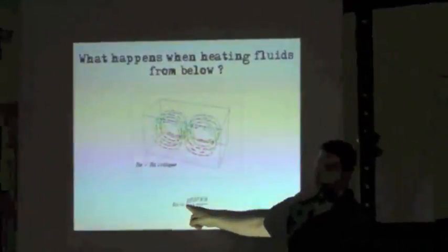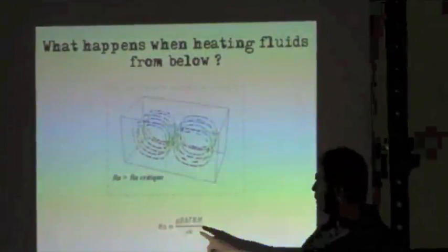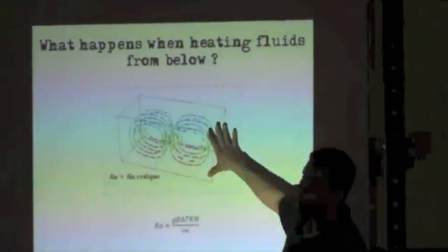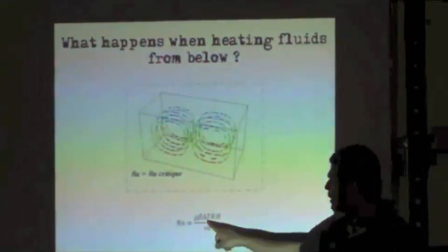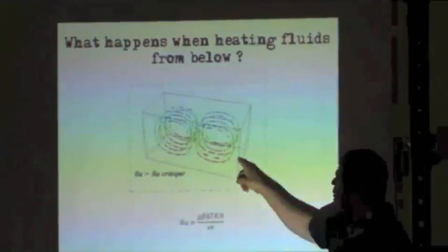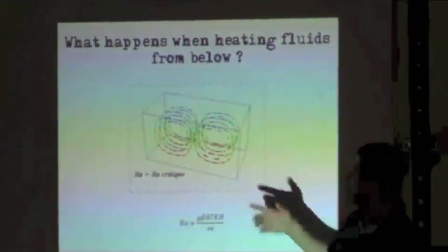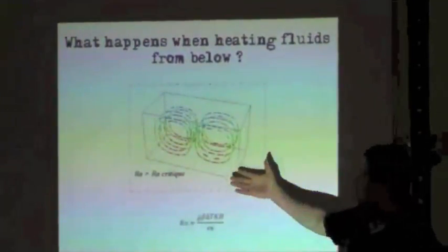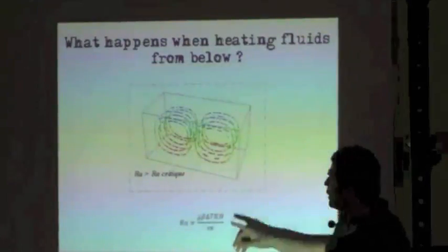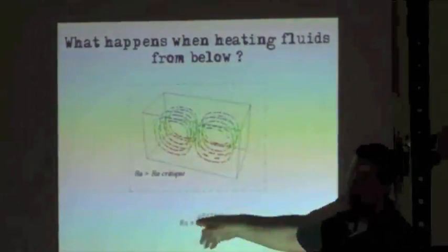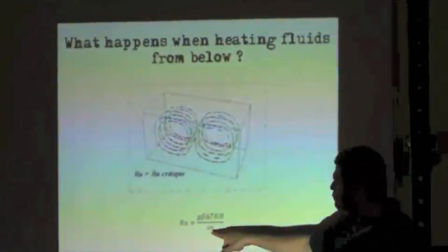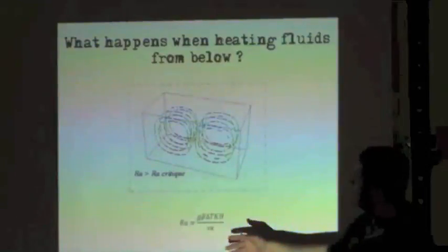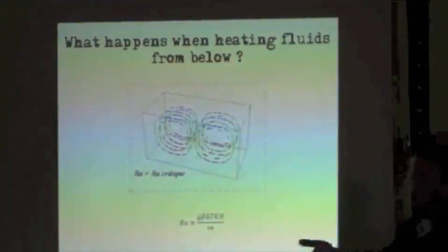It relates gravity, expansion coefficient, permeability, the height of the cavity, viscosity, and thermal capacity. And here we have the gradient of temperature across the two layers. So in a porous structure, we can't control anything in the Rayleigh number because gravity is gravity. Here, these are the physical properties of the liquid, and the delta T is imposed by a geological state.